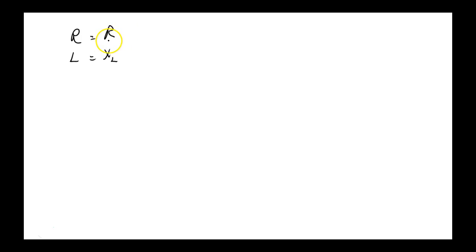Both of these are measured in ohms, remember? This was frequency times inductance, but inductance is an ohm second, frequency is a per second, so that comes out in ohms. Well, the new one is going to be impedance, and I'm just going to write down the word impedance, okay, or at least part of the word, and the symbol for that is Z, okay?